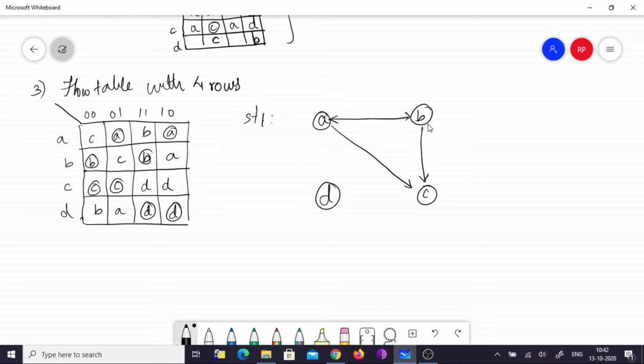Likewise, from C you can go to C, C, D, and D. So this is possible. So from D you can go to B, okay. From D you can go to A again, possible, and from D to D, so that's a self loop. So if you analyze this, let's take a random value. Let's assign some random value to find out whether we have any racing condition here. So definitely we should have racing condition because it's like cross dependent.